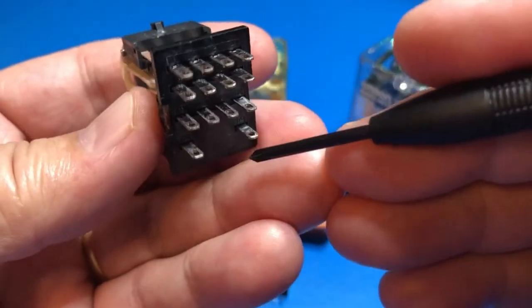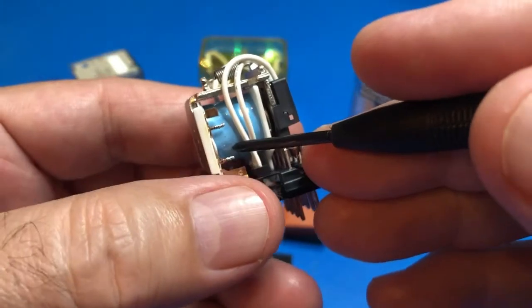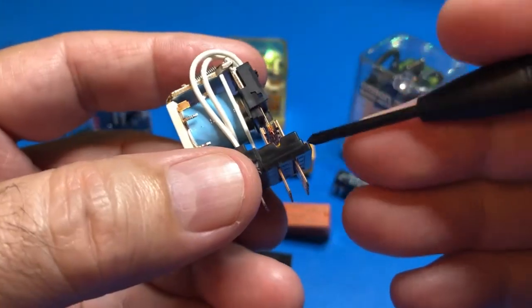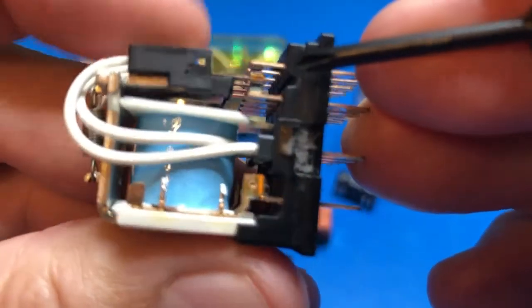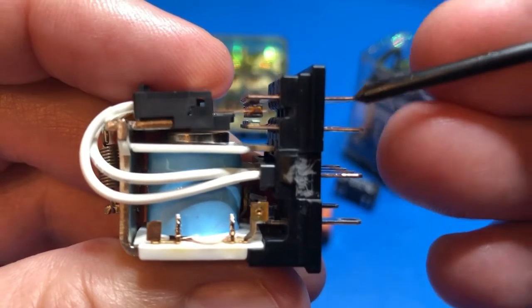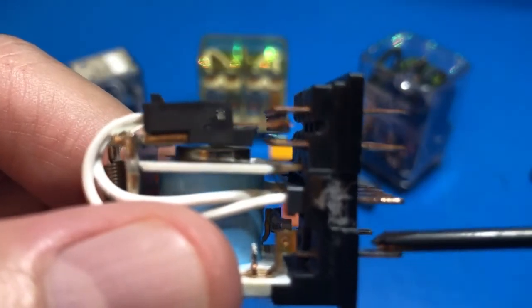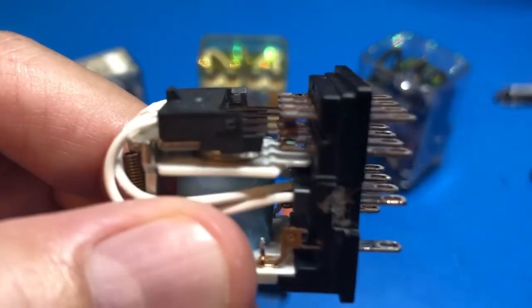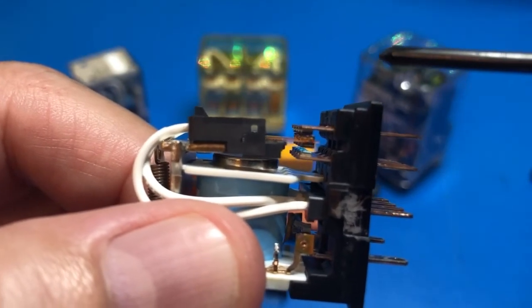When we send an electrical signal between these 2 contacts, this one works like a magnet. And here what we have are the contacts of the relay. It's like a switch where you have a center position that is connected to this side and this other side. If nothing is being sent to the relay, there's no electricity going to this, these 2 are connected. This is what we call normally closed.